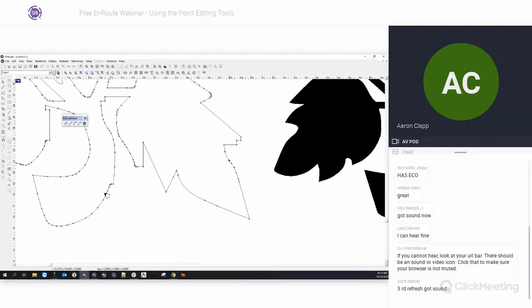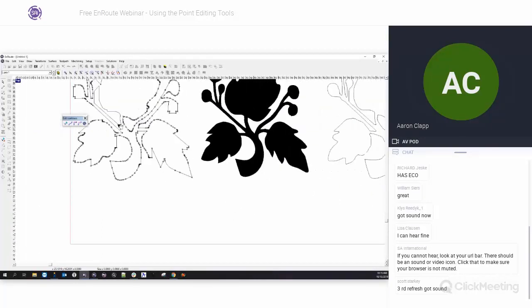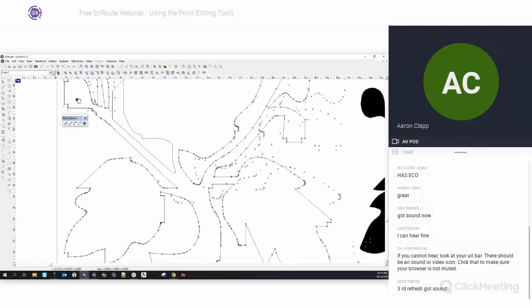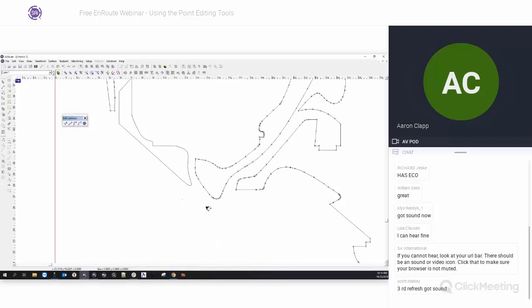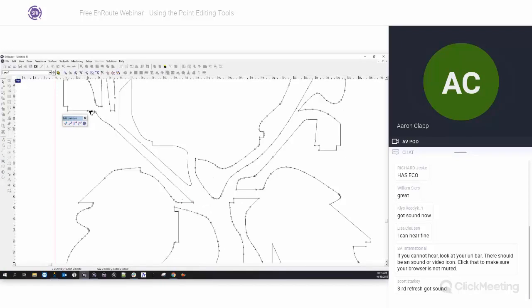Another thing that you might be interested in doing is creating a straight line. Here's a good one. Same principle is what it uses. So I'm going to select a point down here, and let's say I want it to end right there, and hit enter, and it'll simply straighten that line out for me, regardless of how many points I put in here.